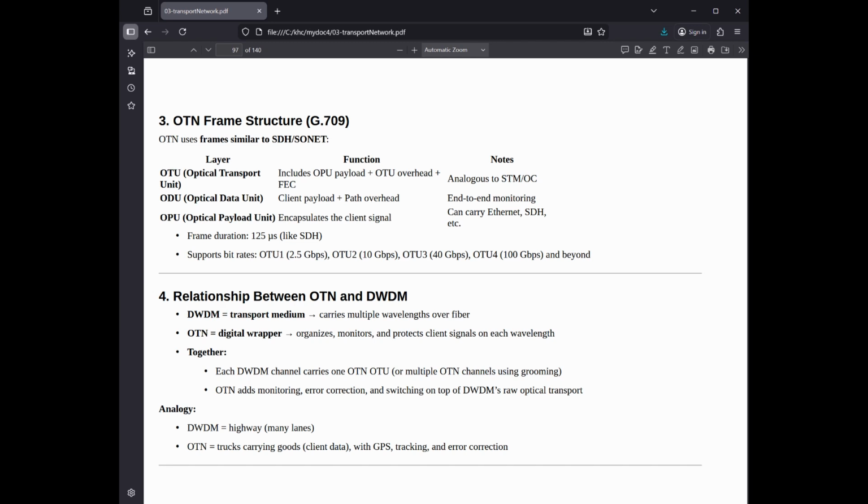compared to ATM. 3. Forward error correction, FEC, columns 3825 to 4080. This is the security seal at the end of the container. The last 256 columns are dedicated to FEC using complex algorithms, like Reed-Solomon. The receiver can correct bit errors on the fly. This significantly improves the signal-to-noise ratio, SNR, allowing for higher speeds over longer fibers.